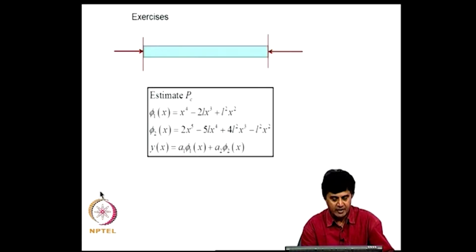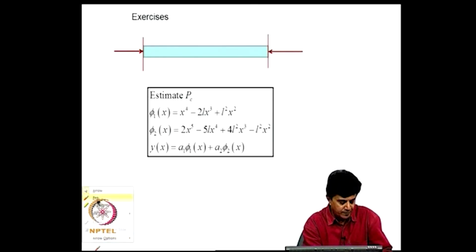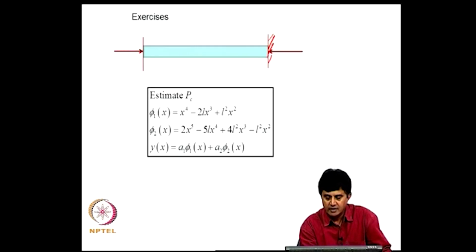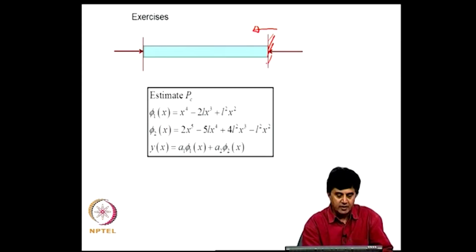The Galerkin method we can use for a few examples. For example, consider a beam fixed at the two ends carrying axial loads as shown here. Again I want to recall that this fixity convention that we are using here should be taken to mean that the translation and rotation here are 0, but the axial deformations are permitted. Otherwise this load will not do any work on the beam; that is not what is meant by writing this fixity condition.